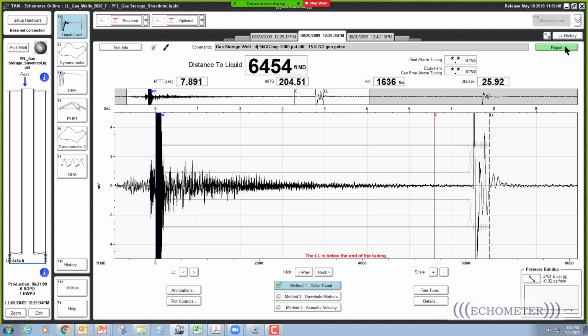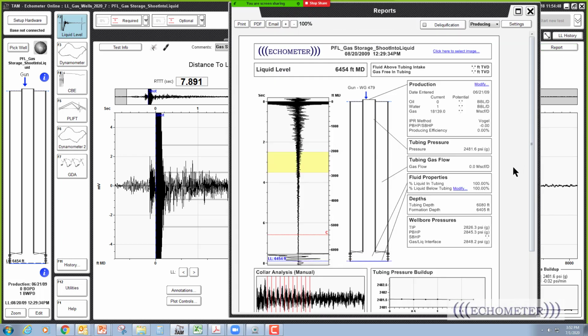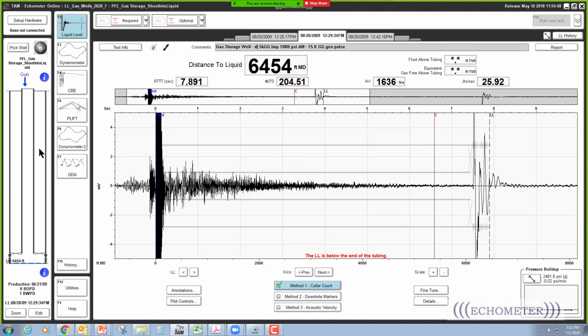Let's go to the report. The report says the pressure right there is 28, so it's a little less than that. So maybe the packer is not the leak, and maybe it is. I'm not sure why there was pressure leaking in, because the pressure at the packer is going to be less than the pressure down the tubing if it's filled with water. With that high gravity, I don't know if it's 1.17 or not. All right, so that was this well.